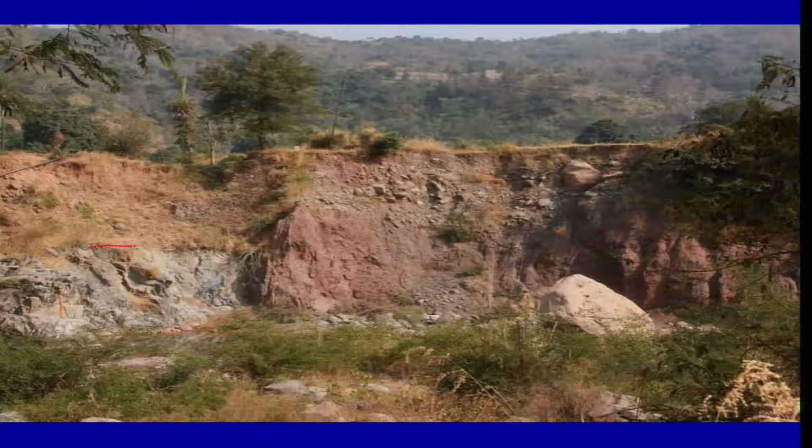So, we have a bedrock here. This is the level of the bedrock, and here on this side we have the level of the bedrock. And this is what we are marking as a fault here. So, there is a displacement where this block has moved down, this has moved up, and so this is a typical strike slip fault which we are looking at, and probably we are having a thrust component in this, where the right hand side has moved up compared to the left one. So, this is what we come across if we have to look at the shear zone. So, we need to avoid putting structures on the top of this.